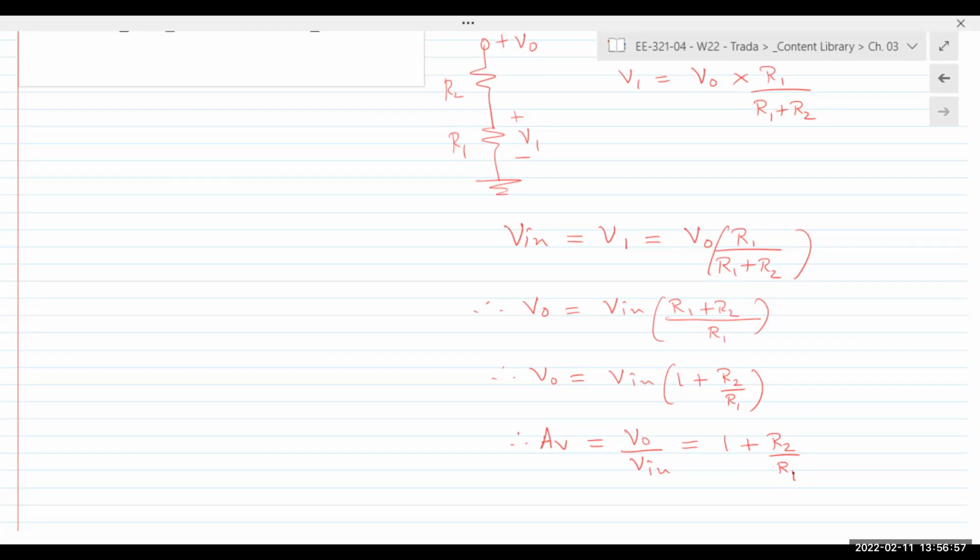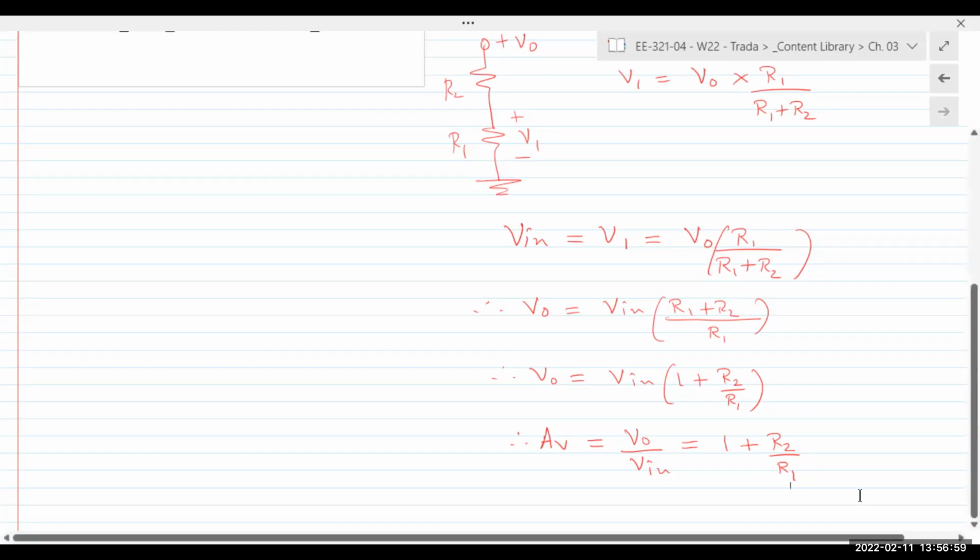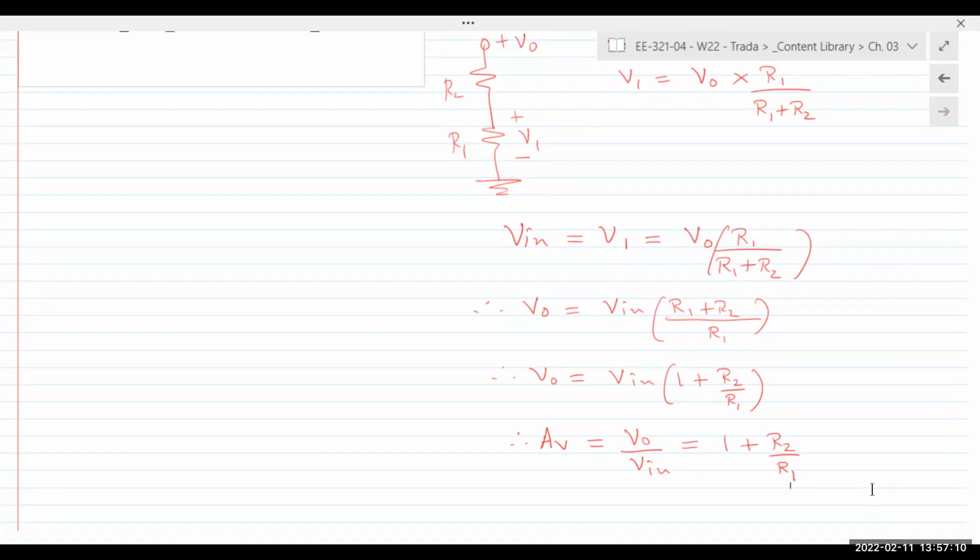able to apply the basic KCL techniques, which I have 3 minutes. So I'll do an example in that time. So you should be able to apply simple analysis technique and be able to determine what the currents and the voltages are for those resistors. If you're provided a circuit with different resistor values, you should be able to calculate the gain or the output by applying these equations. And since if R2 is 10 kilo ohm and R1 is 1 kilo ohm, gain is 1 plus 10 equal to 11. And you should be able to calculate the output based on that.